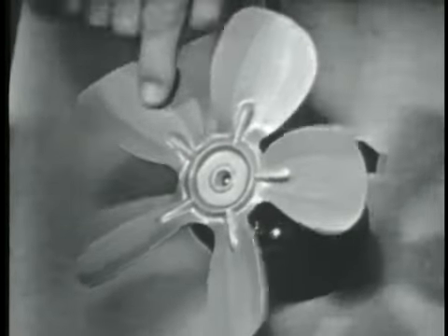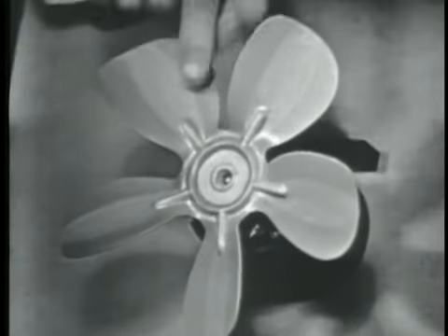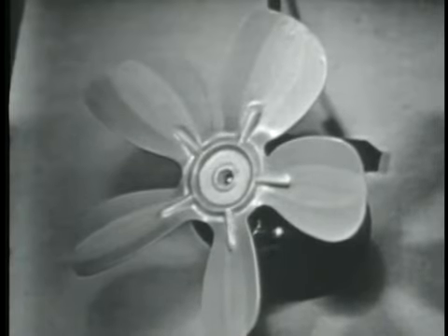Very good. Now, when we put this fan blade on the rotor, we have increased the load or the drag on the motor. And therefore, it's going to turn a little slower. In fact, I've got to give her a little start there to get it going. Now, it turns slower. Now, before, the rotor was turning almost as fast as the magnetic field, under a no-load condition, of course. Right. Now it slows down a little. Well, it slows down a lot because it's got work to do. There's more drag on it. Right. So the rotor does then turn slower than the magnetic field. I think we've proved that point, Bob.